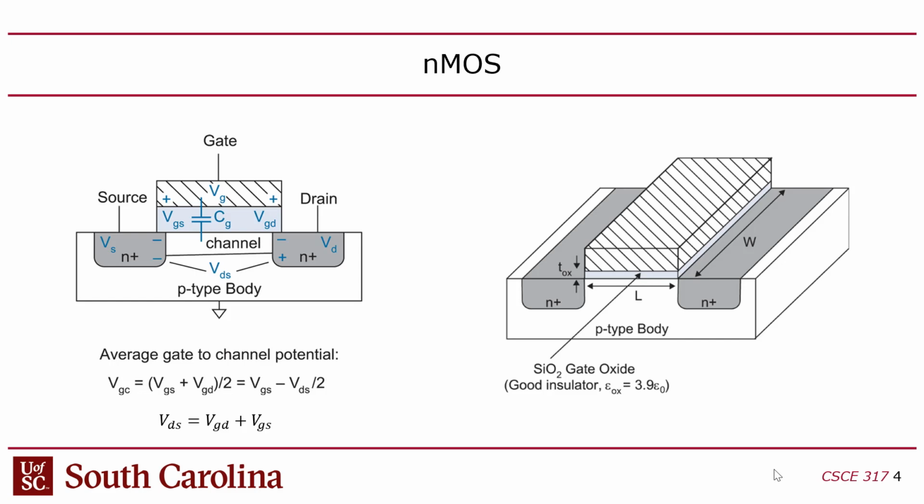The reason it works is because you have a capacitor there, but it's also kind of unfortunate, because it's what limits your switching speed. It takes time to build up the charge. There's a time constant, so it's going to take time to turn this off or turn it on, and thus chips are not faster than we want them to be.